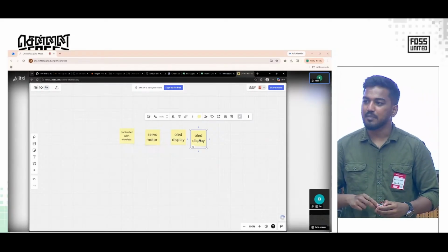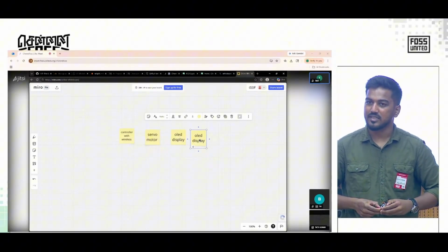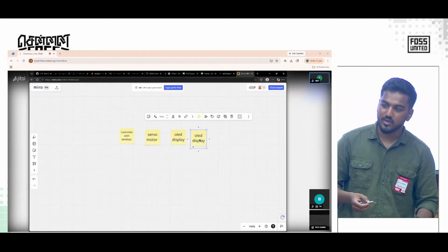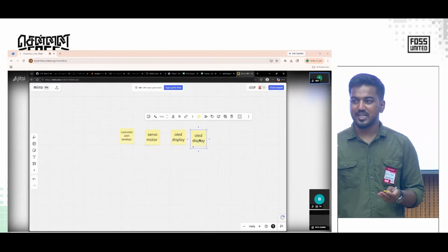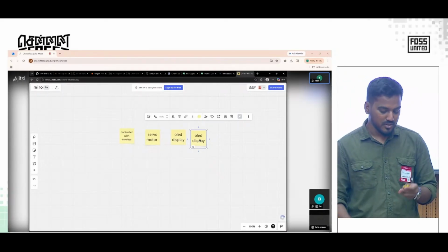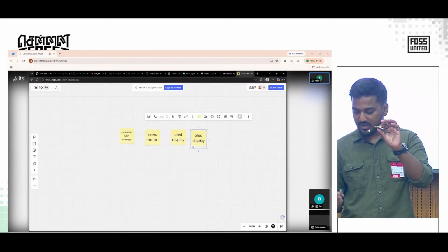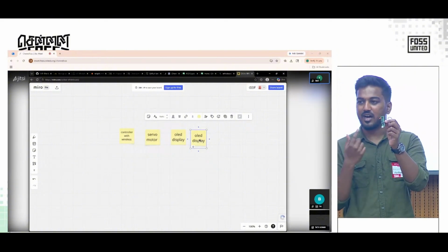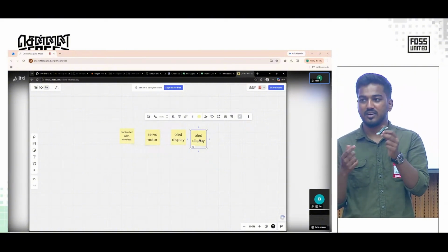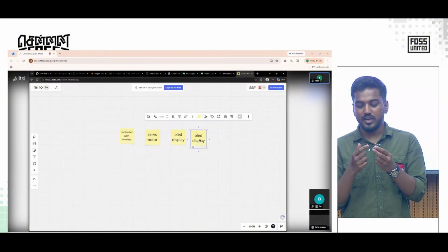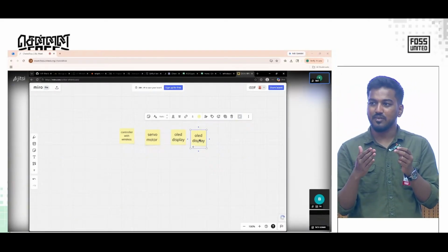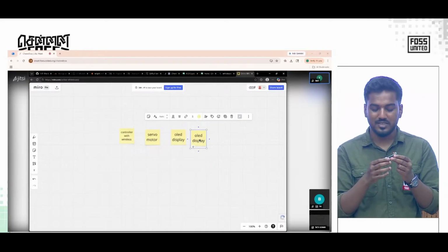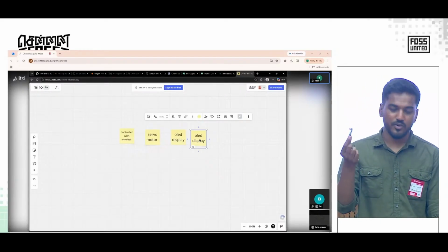The battery that we use is 3.7 volt. But the servo motors or other motors usually run at a much higher voltage. They need at least 5 volt or above. So we take this 3.7 volt, it goes inside this sheet and is converted into 6 volt. That will power only the servo motors. We have divided the power, and all the power management, all the complex stuff, is handled on this board. So you don't have to do any of that.